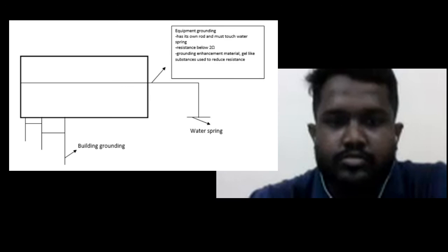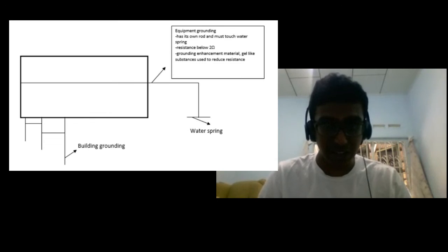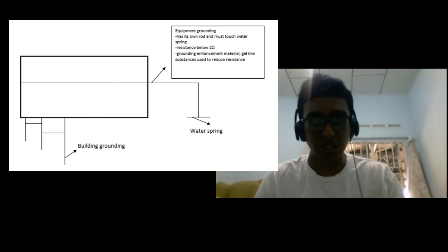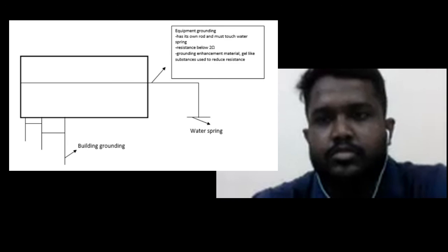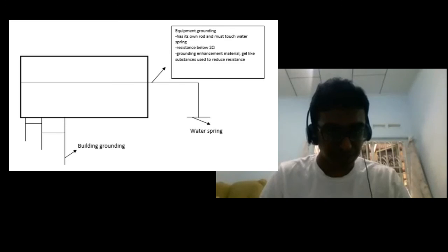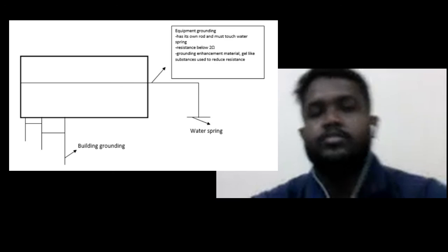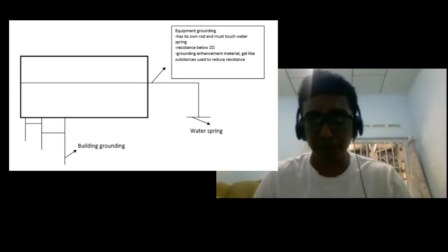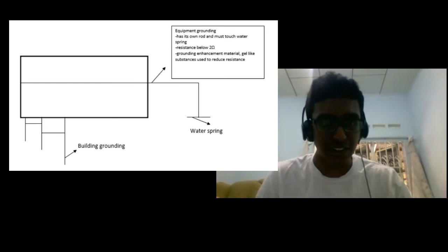The kit is grounded separately at only one position to the ground rod, to avoid ground loops between grounding points. Okay, from the building, we can see that the normal grounding is separate from the equipment grounding. Our frequency converter has its own grounding rod.